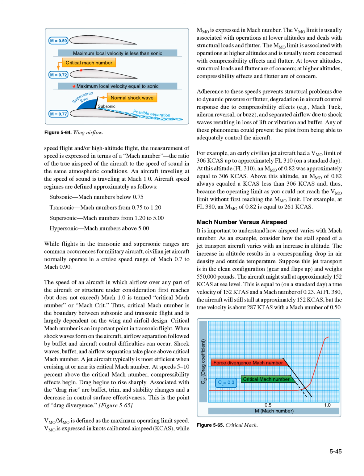Adherence to these speeds prevents structural problems due to dynamic pressure or flutter, degradation in aircraft control response due to compressibility effects, for example, Mach tuck, aileron reversal or buzz, and separated airflow due to shock waves resulting in loss of lift or vibration and buffet. Any of these phenomena could prevent the pilot from being able to adequately control the aircraft.